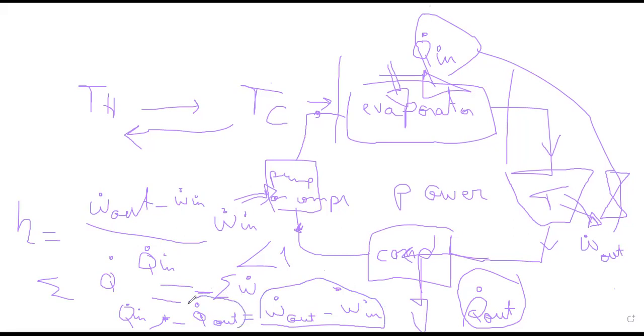One very important way to enhance this efficiency is to use heat recovery. What do we mean by this? The flow exiting the condenser, you can have gases, for example, that will enter the condenser and take energy from the fluid. These gases, when exhausted, instead of being lost, we can pass through another heat exchanger, for example for another power plant.